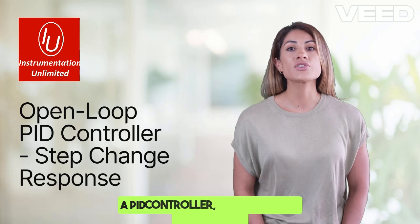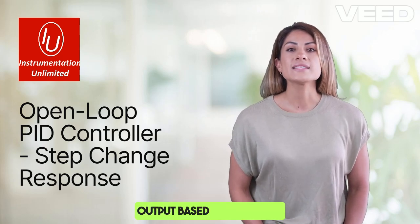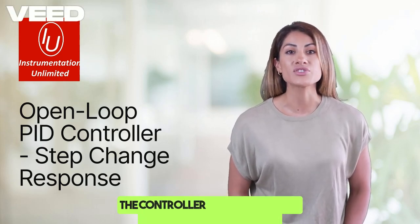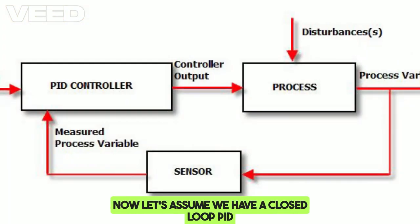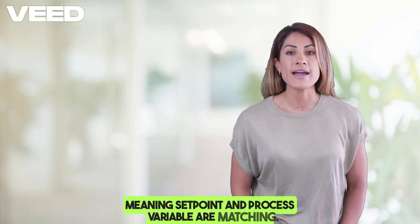A PID controller, proportional, integral, and derivative, usually works by adjusting its output based on feedback. But what if there's no feedback? That's an open-loop PID. The controller responds purely based on the input signal without knowing what actually happens in the system. Now let's assume we have a closed-loop PID controller for a process and it's operating stable, meaning set point and process variable are matching.